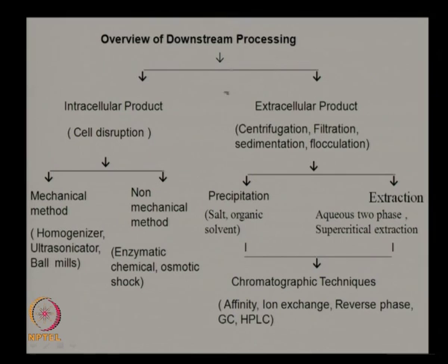But if you are having an extracellular product, you are not interested in the biomass or the microorganism, you can throw the microorganism out. So you use a filtration technique, you can use centrifugation techniques, or even sedimentation. Sedimentation is nothing but a settling technique. So if the solids are very heavy, they settle down, so the liquid on the top rises and you can take your liquid because your product is in the liquid.